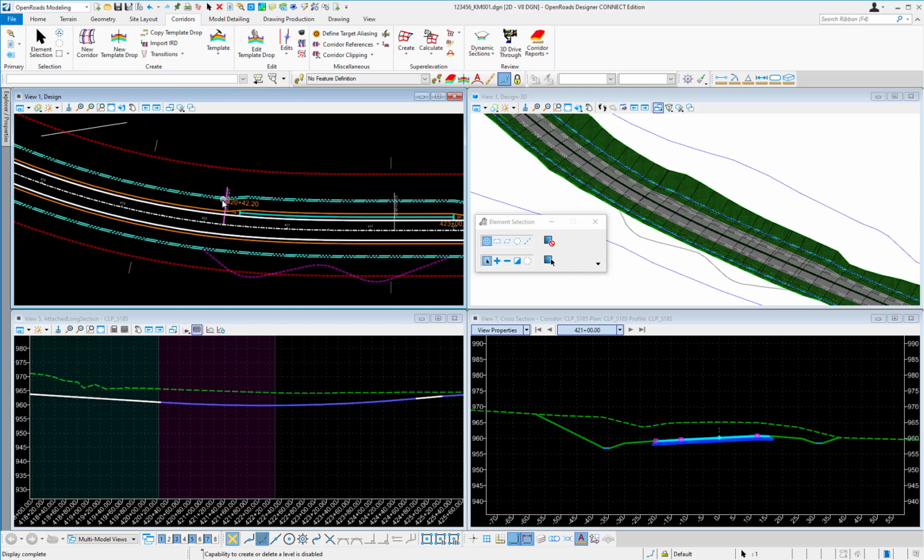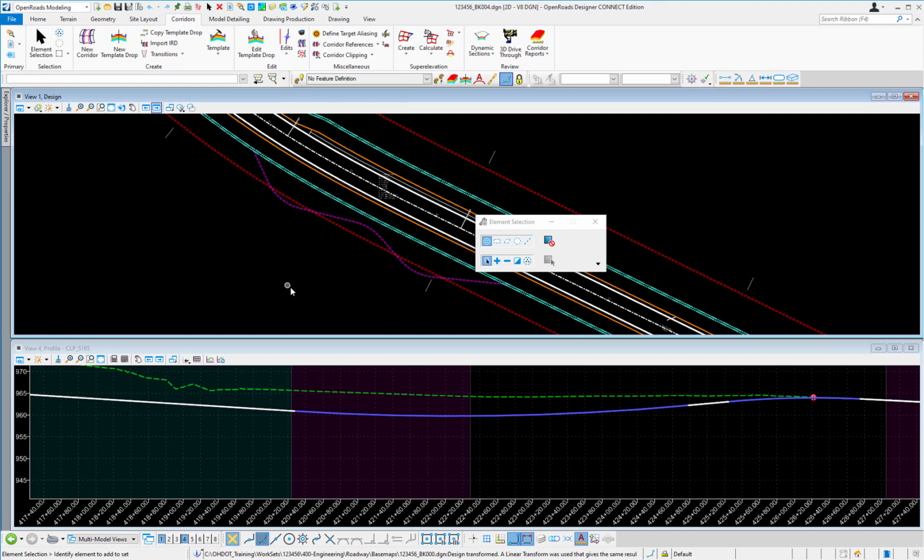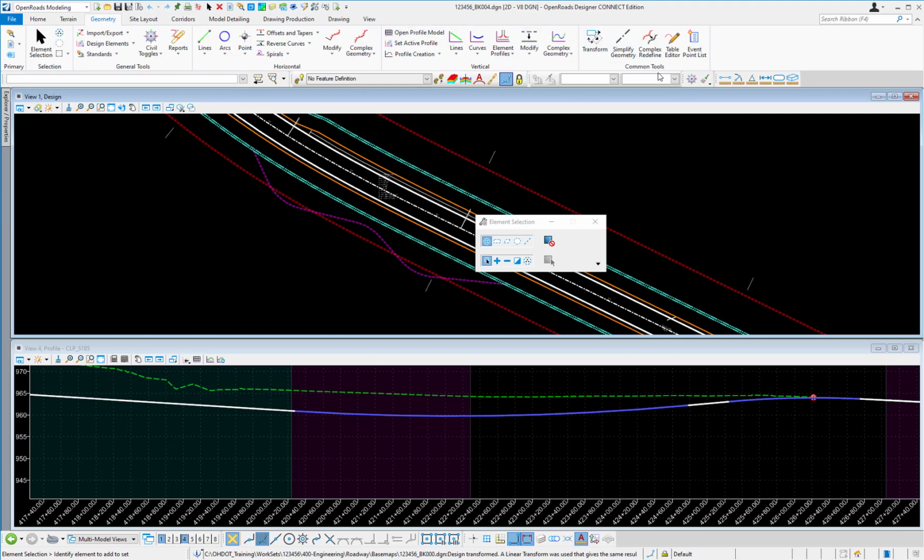So now what I want to do is look at adjusting the left ditch to follow a profile that I need to define. So I'm going to switch over to the geometry base map file for this corridor. And I already have my profile view shown here. So from when I switch to geometry, I'm going to toggle on my Civil AccuDraw, and I'm just going to place a simple profile by PI here.